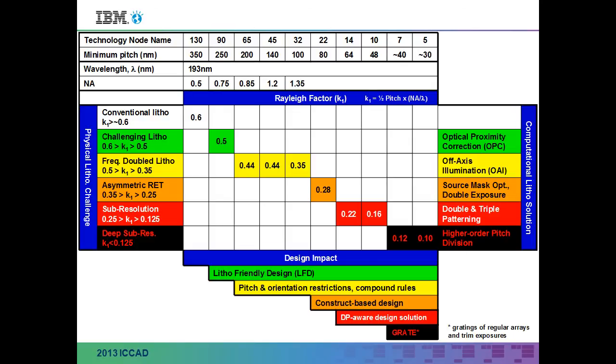So as a lithographer, you kind of classify the technology by the minimum pitch that has to be resolved, and typically it's one of the 1x wiring pitches that forms the minimum dimension. So that's the second row here. Then I have wavelength. It's not a very exciting field. It's all 193 nanometer light, and of course that's quite central to this whole talk, and we'll talk about that some more. The numerical aperture, which is the second big resolution knob in lithography, right? You can see how that is increasing.